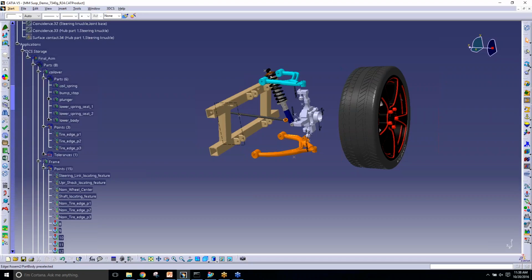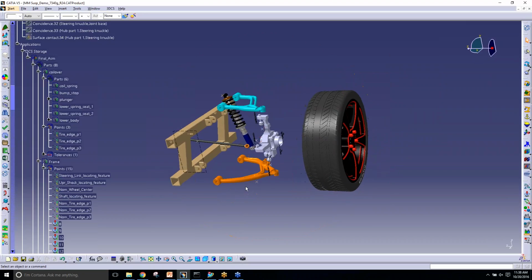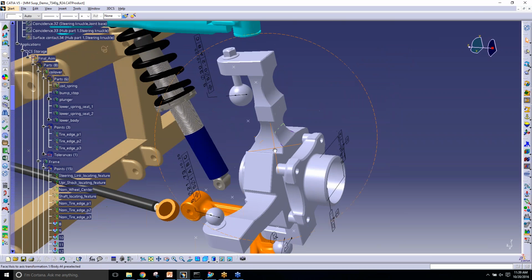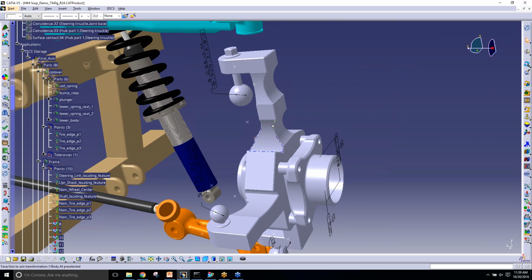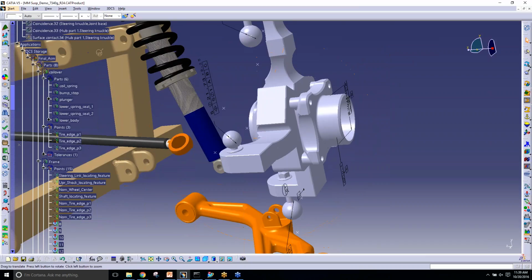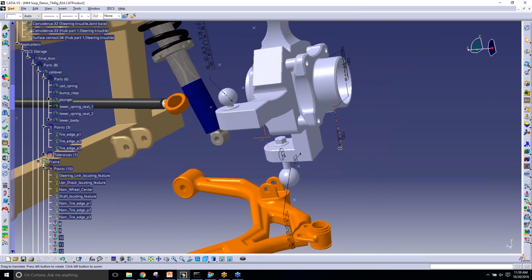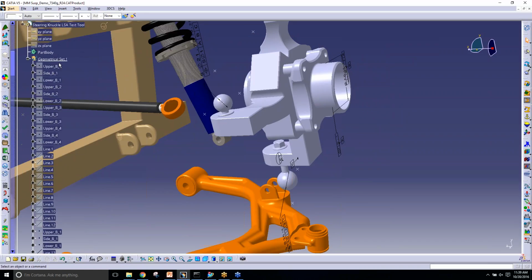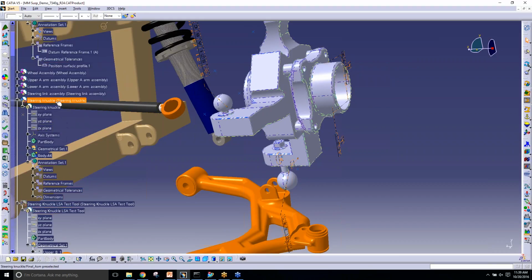Oh, sure. Yeah. So a fixture is usually something that we reference, or 3DCS will use to reference an actual manufacturing fixture. So we can take the actual CATIA data. Say, for example, we already have these 3 balls in here, these spheres. We have CATIA points on them, and that can actually be used in a fixture. So if I'm going into, let's see, find the knuckle.